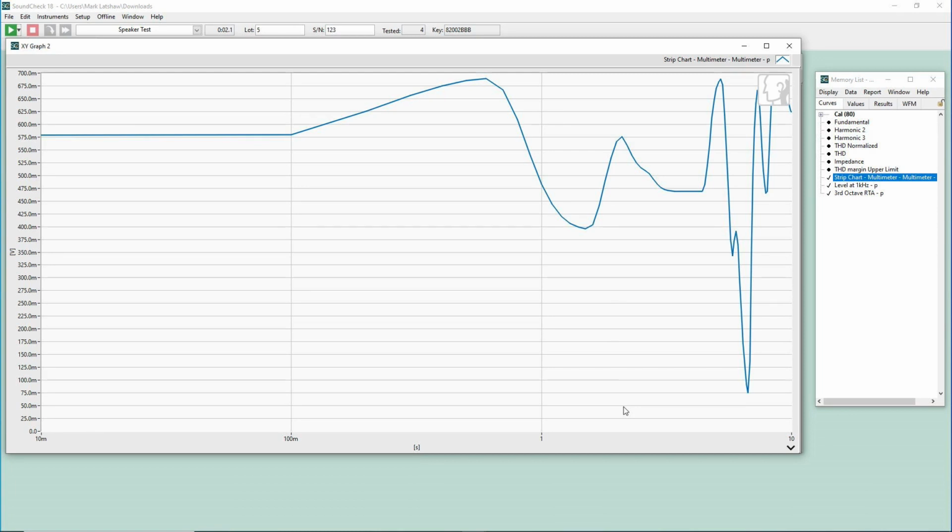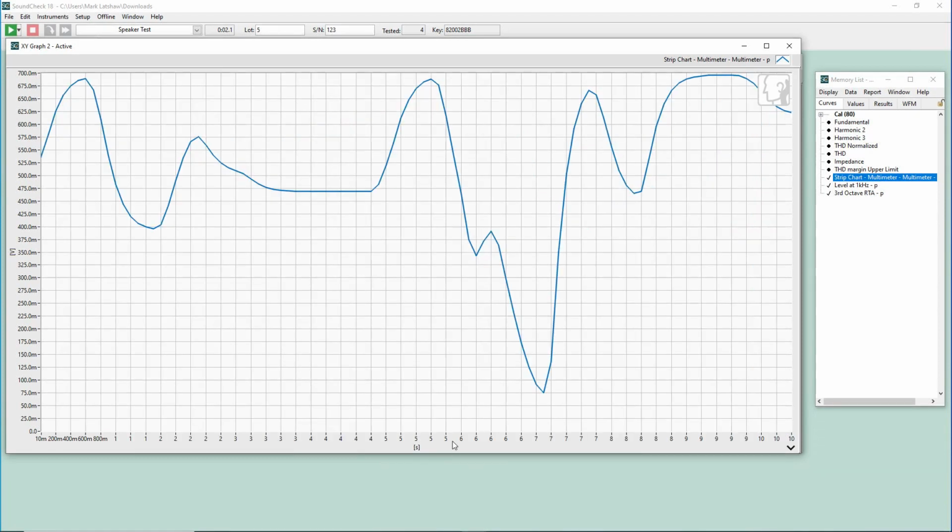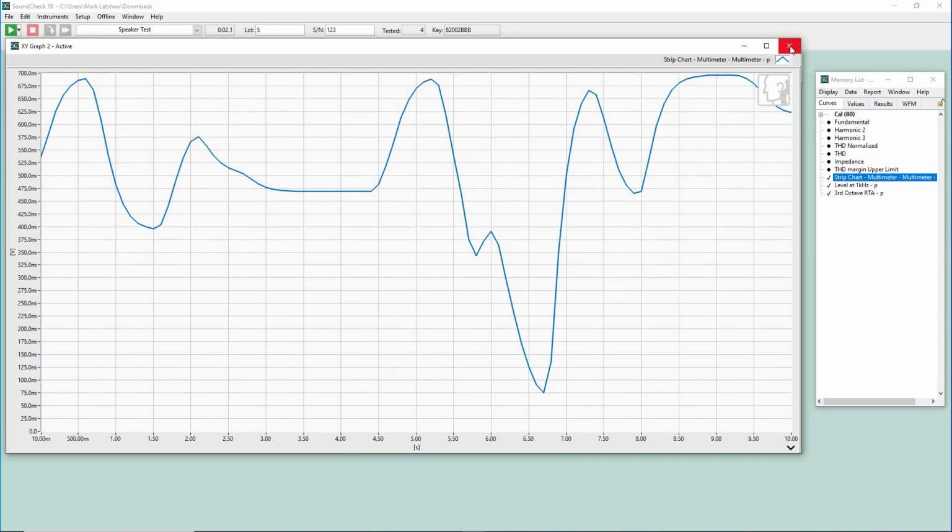On this example though, I just had the time set to relative. It's showing me the time as logarithmic, and that doesn't really make any sense. Here I would want to change the x-axis mapping mode to linear. Now it's showing my x-axis from 0 to 10 seconds in linear mode, and I can view my curve the way that I need to.